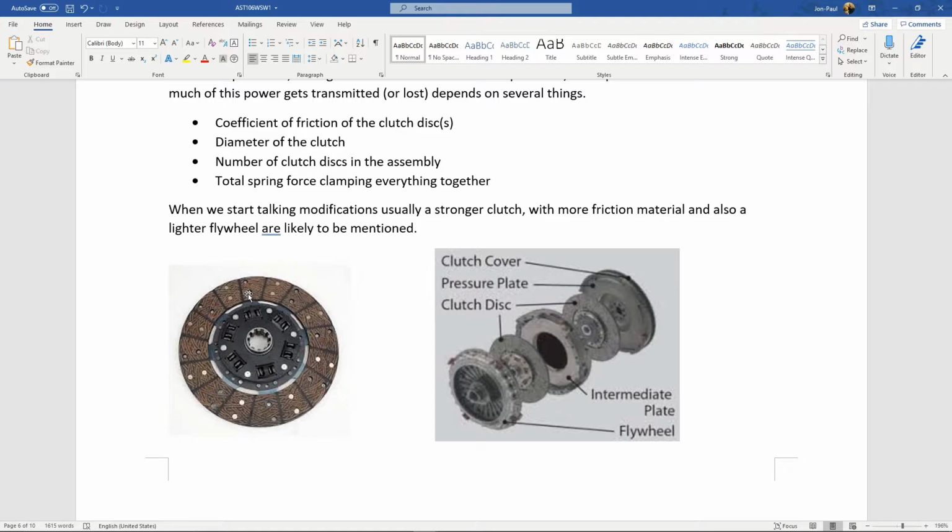That sucks because every time you go to push the clutch pedal down, you're having to fight this very, very strong pressure plate. Some other things are going to be, I now want the new assembly to be lighter. So higher quality materials, better machining processes means money, money, money. In this discussion, I fall back on Exedy clutches. You'd think I was being sponsored. If Exedy, if you hear this, what's up, bro?